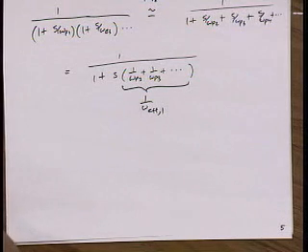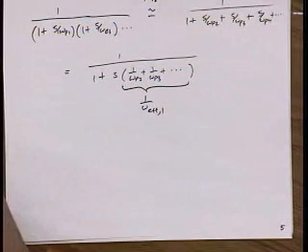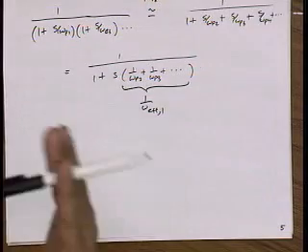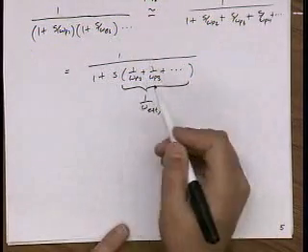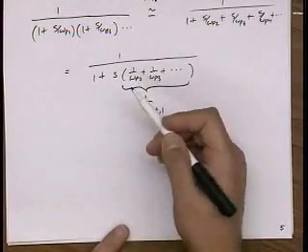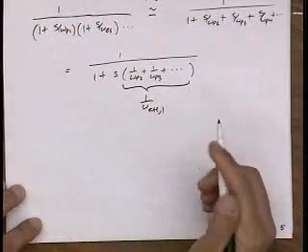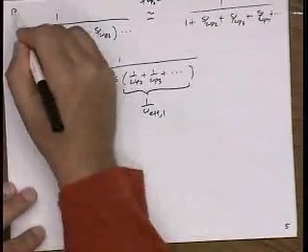So if you had a bunch of non-dominant poles, let's say you had 10 poles at 10 times higher frequency than you care about, well, they all will contribute an equivalent pole at the frequency you care about. So that would contribute 45 degrees. So if I had 2 poles, right, of equal magnitude, their net effect would be roughly half that frequency, right? And so on and so forth. Well, now let me treat the zeros. So these are the poles.